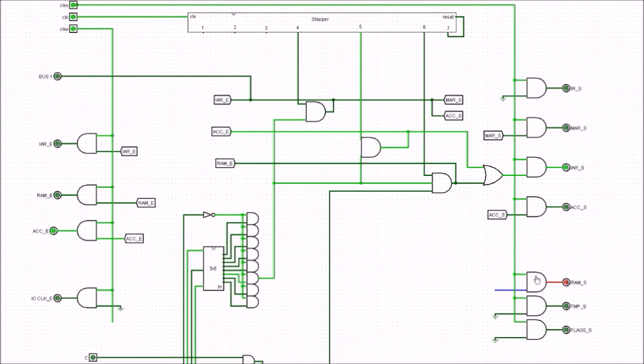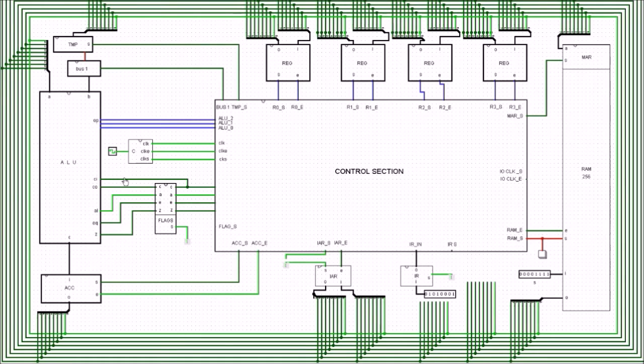But you'll note here that there's a little red line. Red lines should be warnings, because that's really an error. Now I can't show you the full simulation run all the way through to stage 6, because when we jump to stage 6, the way it's set up at the moment, we're actually trying to change 2 things at once, and Logisim's not happy with that. So you might be saying, well, does that mean the design doesn't work? Well, no, the design works perfectly well, but because I've had to disconnect sections here in order to put inputs in to try and show you how the thing works, in doing so we're not able to run through the entire simulation.